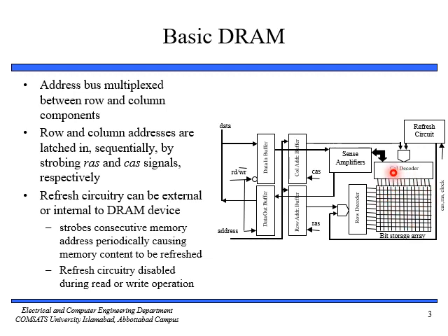So we know that our basic DRAM consists of a capacitor and a transistor. If we do not refresh the capacitor, there will be charge leakage and we will lose the data. So this is our basic DRAM. Here data is coming in, so we have the data in buffer. Here data is going out, so we have the data out buffer.